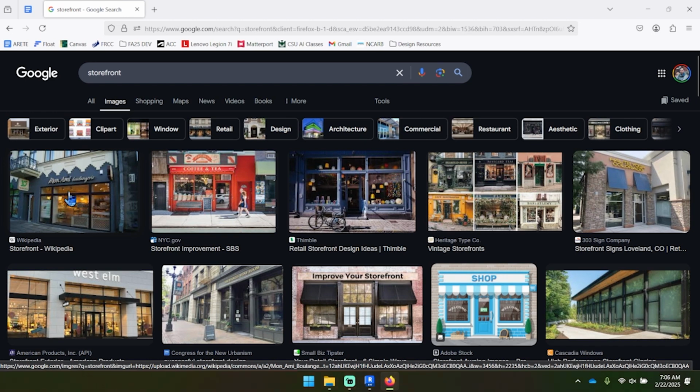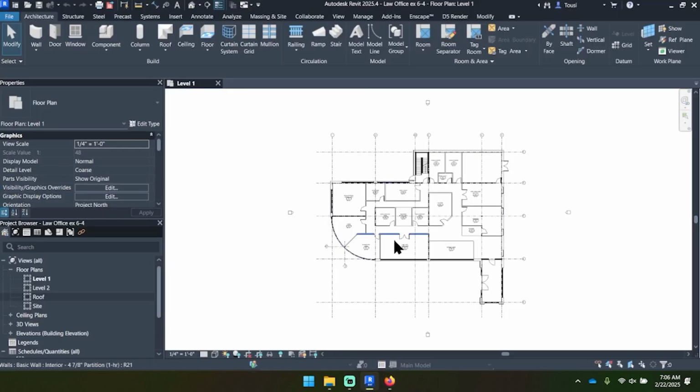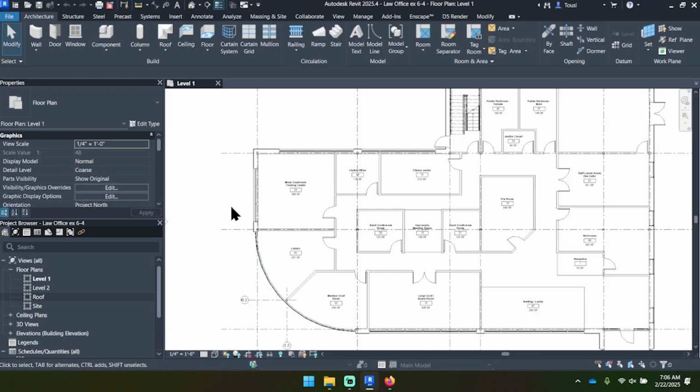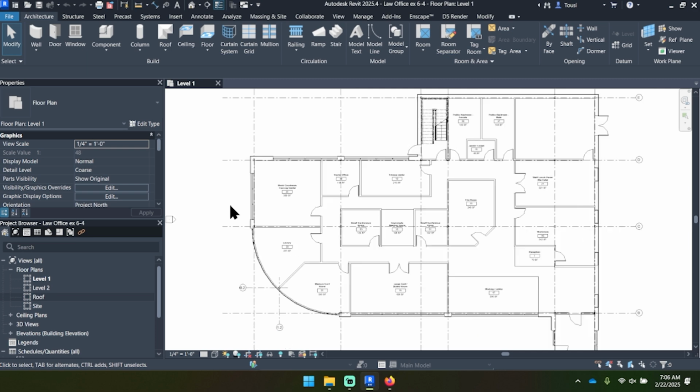This is called embedding in Revit, where you draw a solid wall and then put the curtain wall inside of it. So in that sense, curtain walls will sort of act like doors and windows in that it will cut a hole in a wall in order to add those features. Those are going to be the curtain wall types that we're going to be using most today.